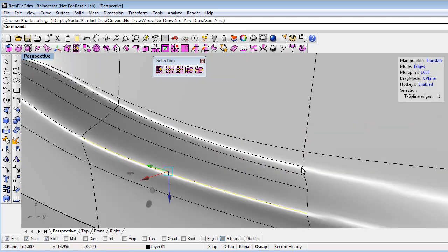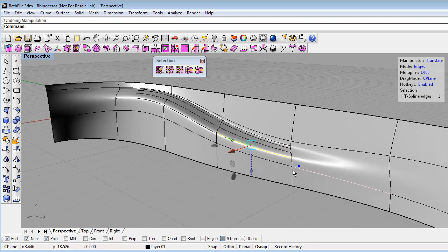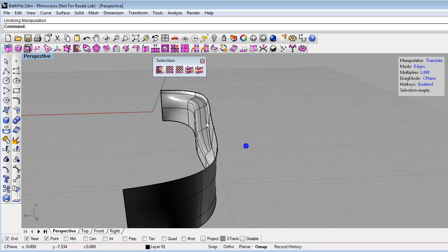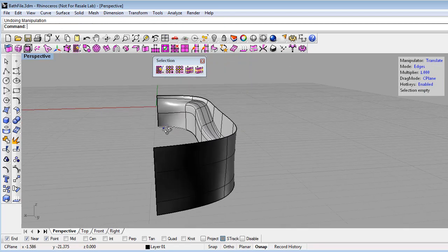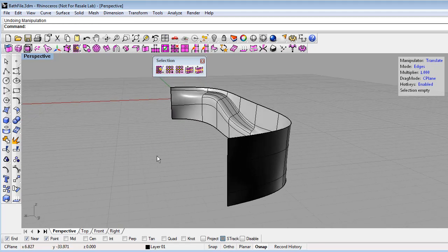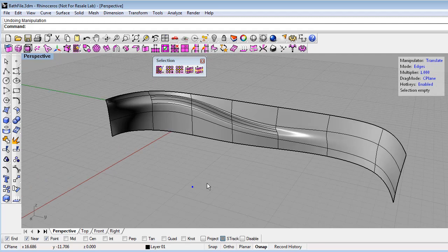These are what we call T-points, and the surface is curvature continuous smooth there. So now what I've done is I've created half of the wall of my bathtub, and if I was creating this in Rhino, I could probably mirror it and then add a bottom on and fillet it and finish off my bathtub. But with T-splines, I have an option of having a little bit more organic control over the surface. So I'm going to create the whole tub as a single editable T-spline.